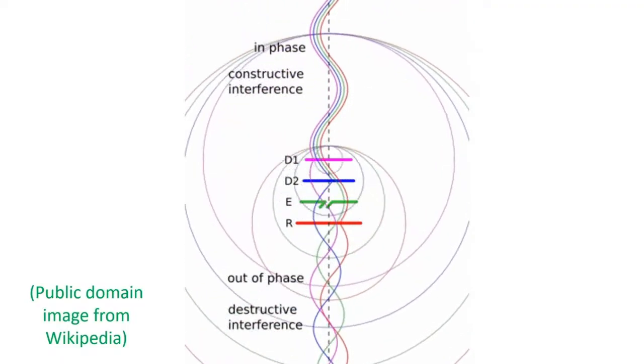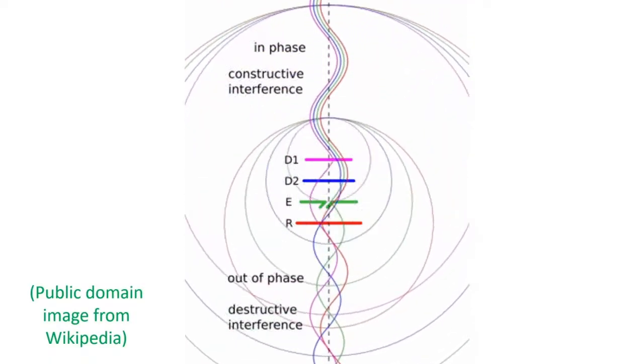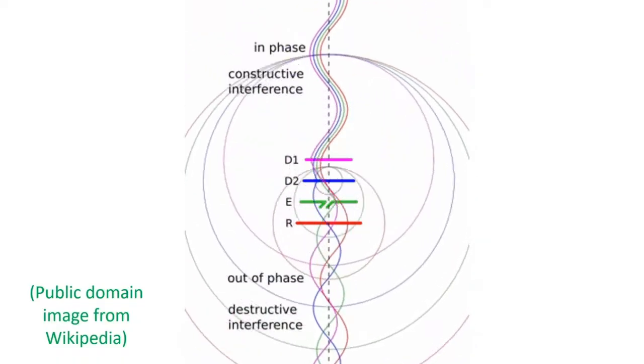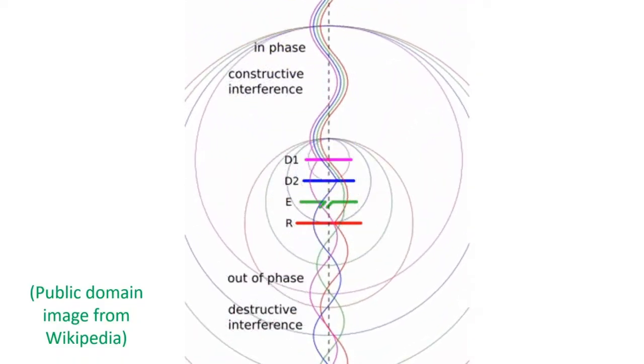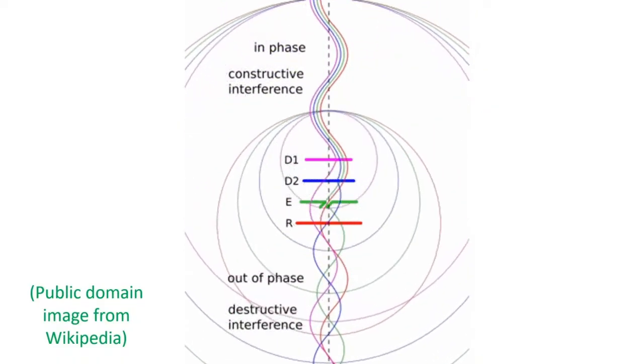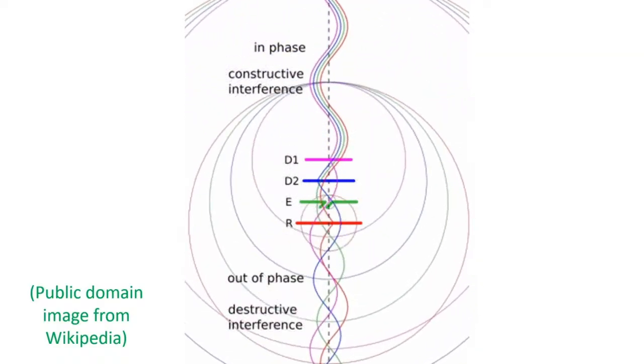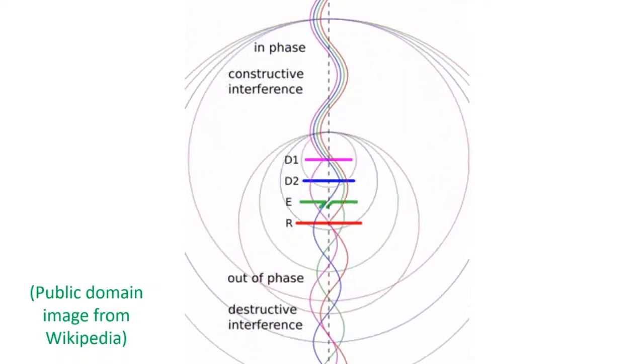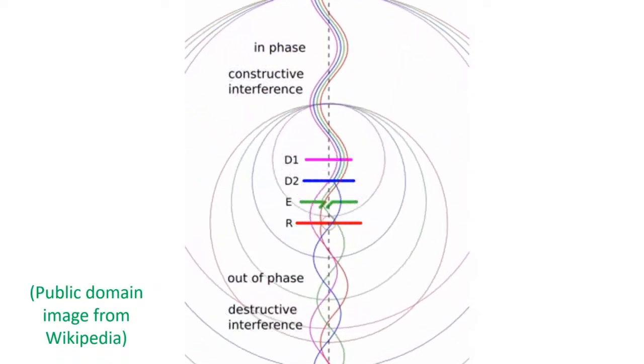Net effect is a stronger signal in the forward direction and a weaker signal in the reverse direction. This is usually mentioned as the forward-backward ratio of the antenna. In the animation, the signals are color-coded similar to the antenna element for ease of recognition.